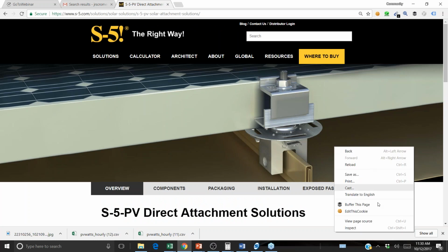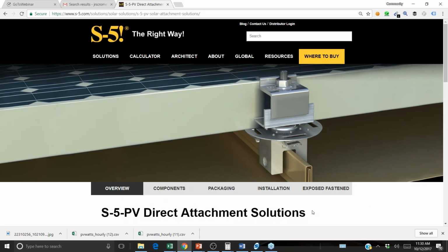Generally when you use these standing seam metal roof systems, you have to go onto every single standing seam, which might be 16 inches apart, whereas in normal solar, when you're directly attaching to the rafter, you're generally going 4 foot on center. The difference between a penetration every 4 feet versus an attachment every 16 inches is easy to skip over if you're a solar installer who's not really evaluating the structural side of the project.